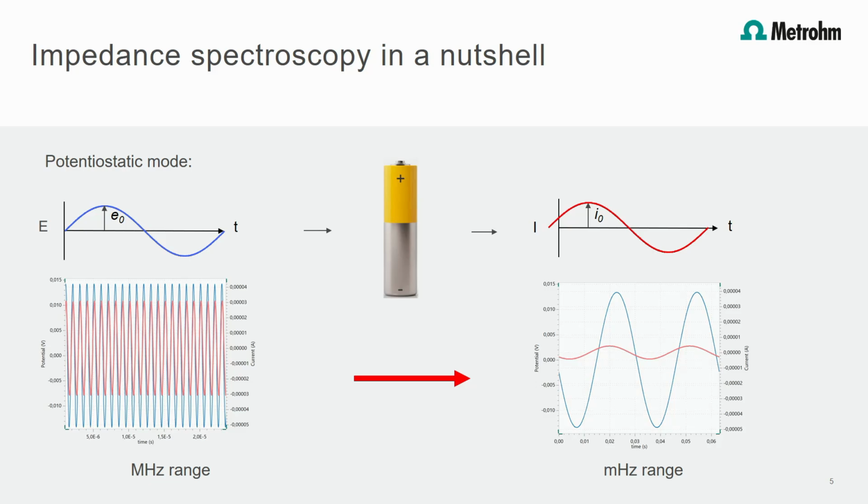So a phase shift in the measured current response indicates that there are capacitive components existing in the battery. With the values of the applied voltage sine wave and the values of the corresponding current signal, the AC resistance, the so-called impedance, is calculated.